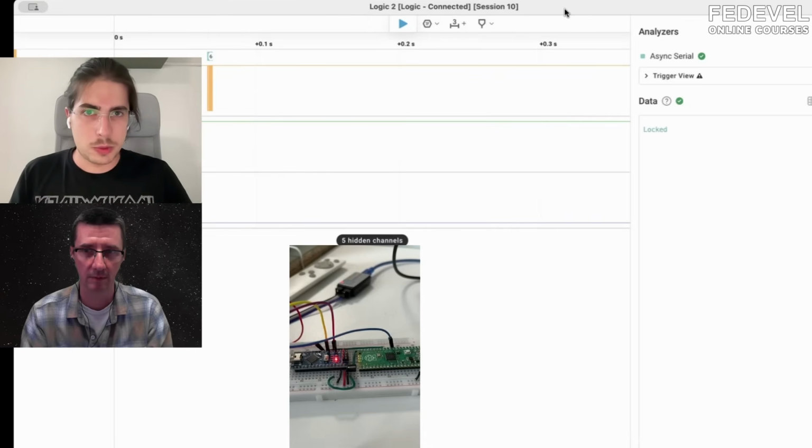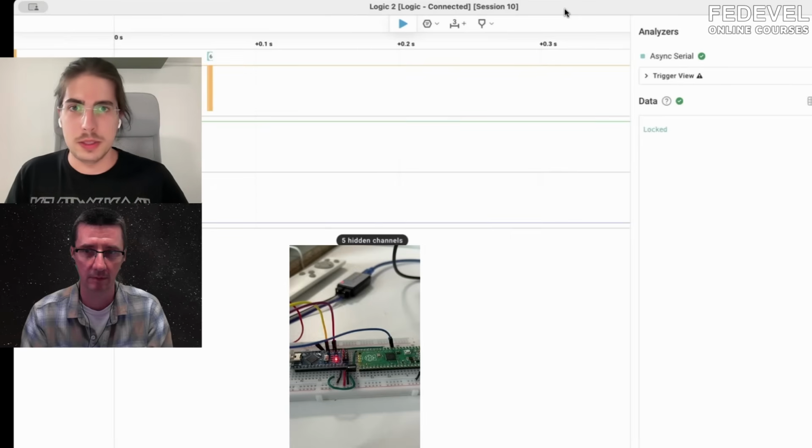This is a demo to make it simple, but imagine instead of this being just count instructions, one of these is an important check or readout of a fuse value. So let's say all of your variables are initialized as 0, and you can glitch all of the readouts, then the variables will stay at 0. And depending on the code that you have, it will impact it a lot.